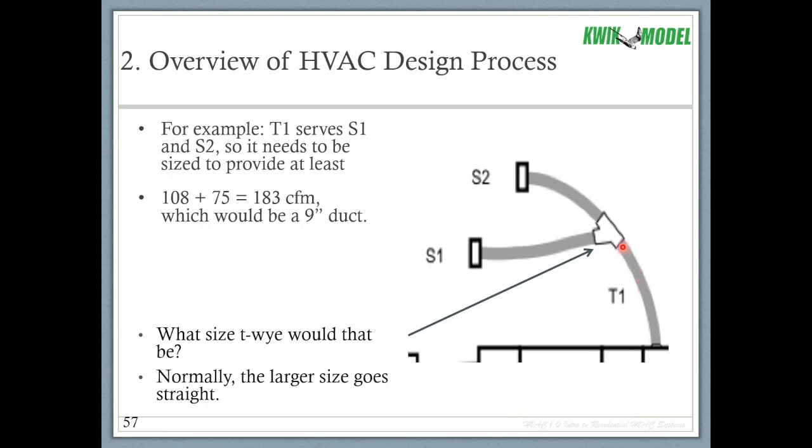So we've got a 9, 7, 6 TY. So this is the 7 as we've sized it, but the way I've drawn it is wrong. So what I need to do is redraw this so that this TY goes straight through here, sort of flip this TY around. So it goes straight through here and branches off to this small one, because this is the 6 and this is the 7 and this is the 9. So 9, 7, 6. So this little TY is drawn wrong, but it's just a schematic diagram anyways, but your final design should be drawn correctly.